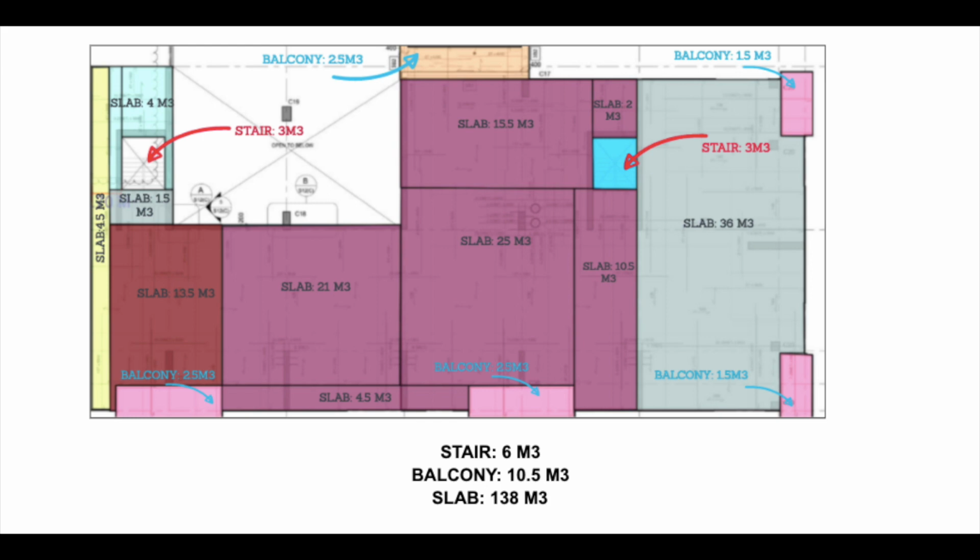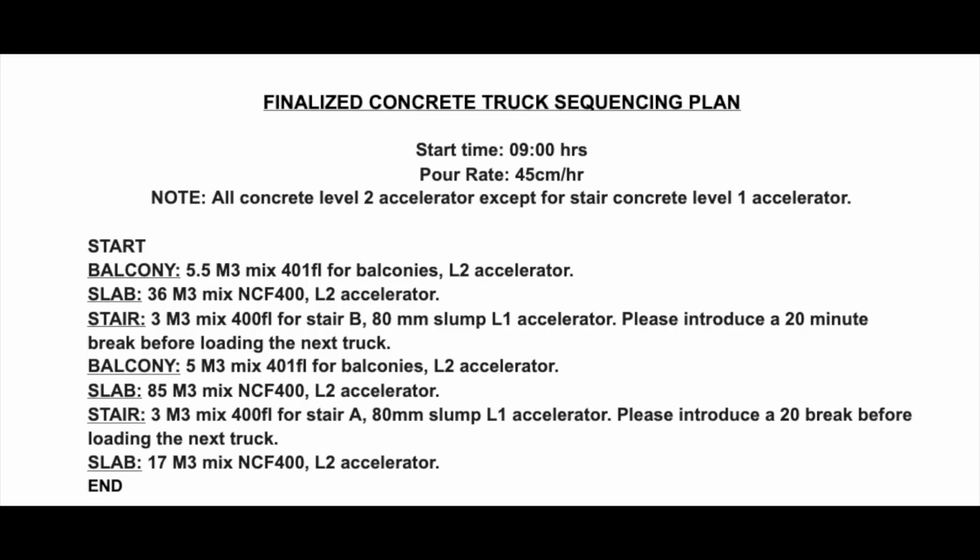And then on this plan, I've broken them out into all of their important areas, and as we are pouring the concrete, I like to supervise the pour on site, ensuring as we hit those certain areas that the volume poured coincides with the plan, and if we need to make an adjustment towards the end, we have the time to do it. So once you've been able to fine-tune your concrete estimate, you're going to then want to send your truck sequencing plan to the concrete plant.